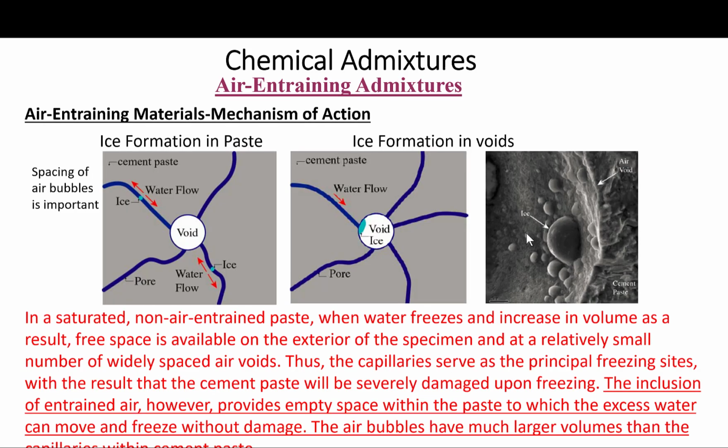This is just a sample slide of what these air entraining admixtures do to enhance the cement paste and eventually the concrete performance in freeze-thaw environments, in cold climates, to make sure we mitigate the potential damage due to the freezing water within the concrete. We will talk about it.